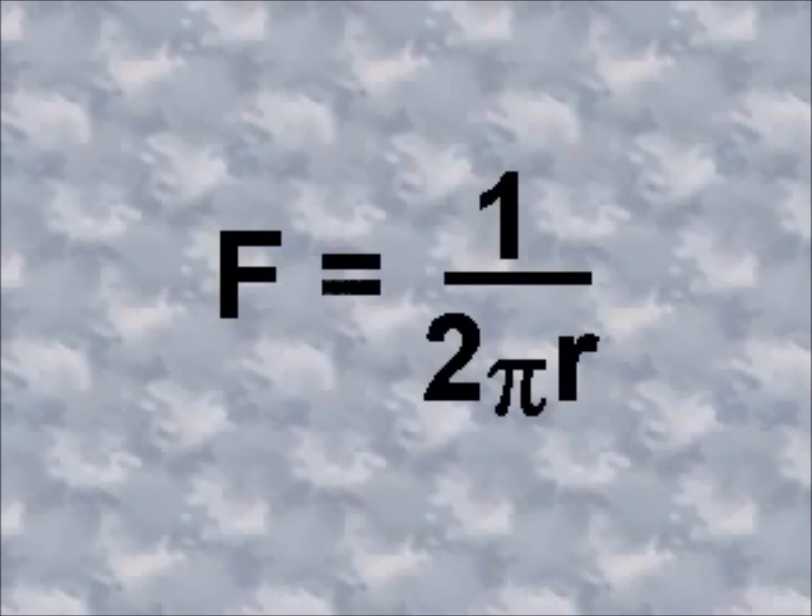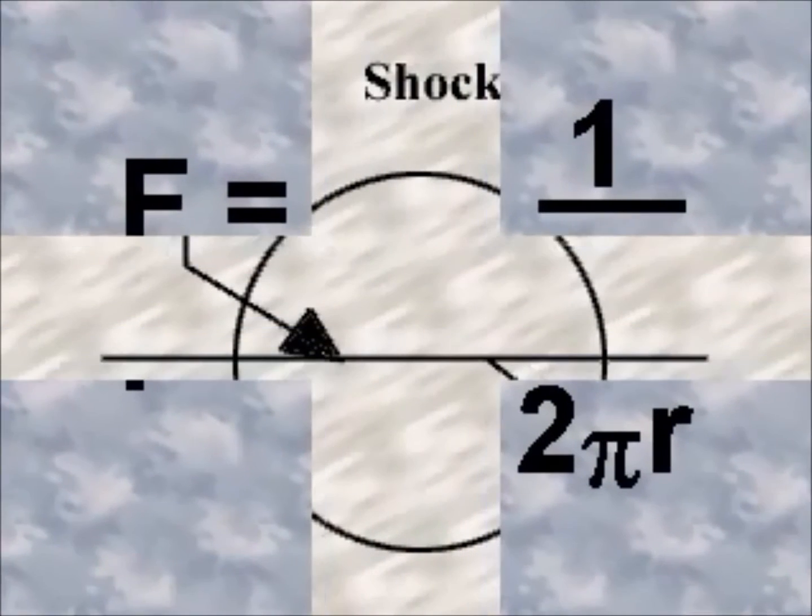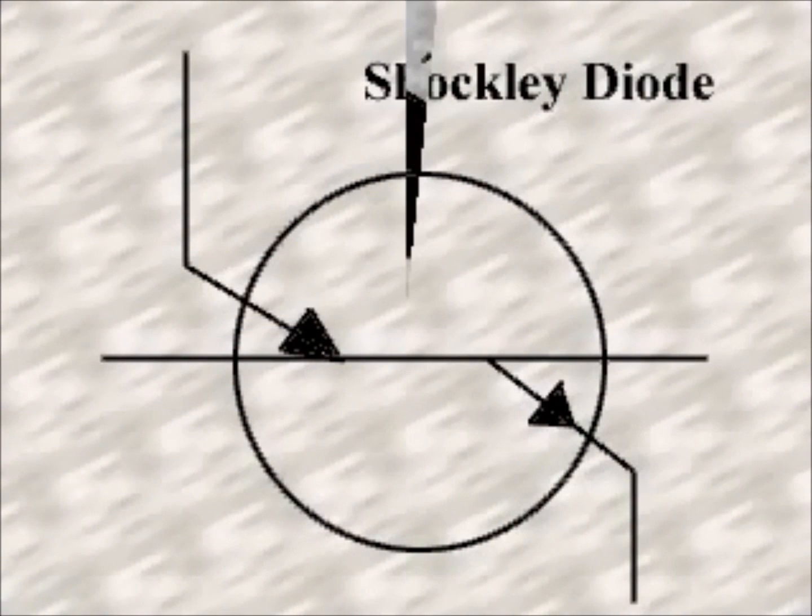The Shockley diode is constructed of two of each type of semiconductors in an alternating pattern. That is, if an ordinary diode can be designated as NP, the Shockley diode can be described as NP-NP. It is also known as the four-layer diode. Like other diodes, it has two terminals, an anode and a cathode. The Shockley diode is used primarily in switching applications. The switching properties are similar to a neon glow lamp.